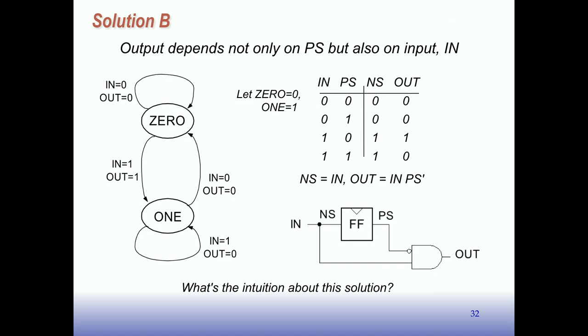And then here, we get a 0. The output goes to 0 when the input is 0 here. And then we go back to the 0 state. Right? So we have 1 fewer states here because we don't have a special state. It's just hold the output as a 1 for 1 cycle. The output going to a 1 happens on this transition here.